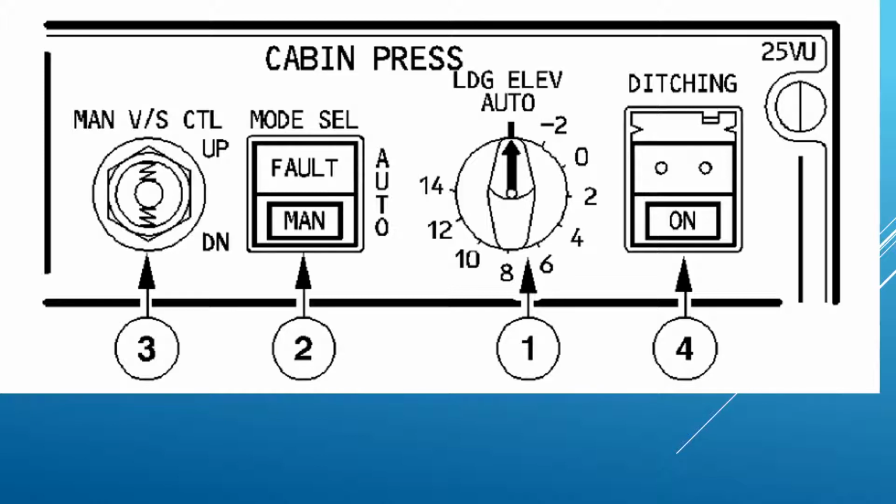What you need to do is push the button to operate it in manual mode, leave it there for 10 seconds, and then push it again to go back to auto mode. It will then attempt to use the other channel. If there's a fault, the fault light comes on, and you can operate it in manual mode.